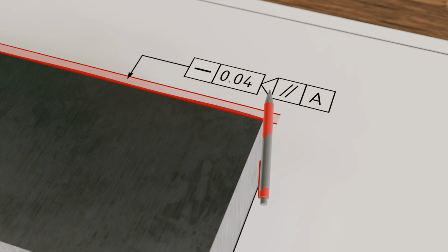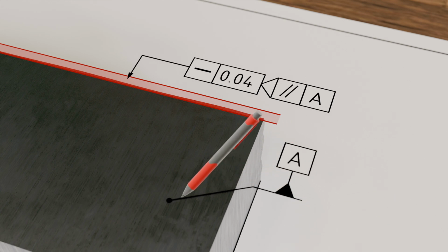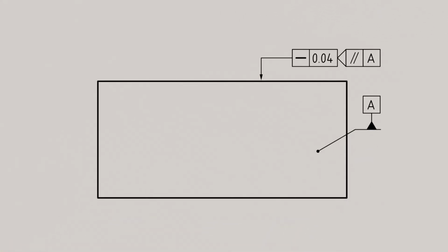The reference itself must then be indicated in the drawing. It consists of a filled datum triangle and a datum frame above it, connected by a short line. The datum letter is entered in the datum frame. In our example, the reference is set on the part surface in the drawing plane and labeled A. In the first box of the section plane indicator, the parallelism symbol can then be entered, for example. This makes it clearly defined in which section plane straightness must be fulfilled: in all section planes that are parallel to the specified datum surface A, which corresponds to the drawing plane.